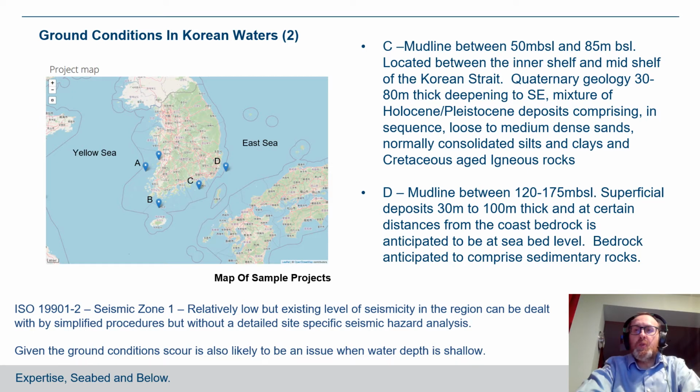Also, with the nature of the ground conditions at the surface deposits, there is also a risk of scour, particularly where the water depth is shallow. So these are two other issues that need to be considered as part of the geotechnical design process.